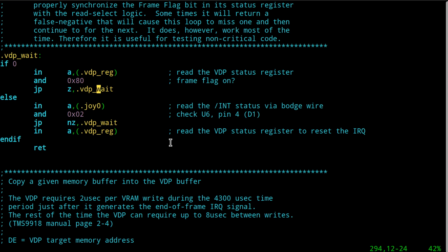But this is running at 60 hertz. So if we waste an entire 60th of a second doing something, disk I/O and things like that can definitely cause these types of things to happen. I can then come in here and start reading this at the point in time when the VDP wants to assert the interrupt signal a second time when it's already been asserted, which can still cause this same race condition weirdness to take place. Obviously, if I miss an entire one, then I will just simply count one fewer than I should have, and you could argue, well, who cares if you're that late anyway?